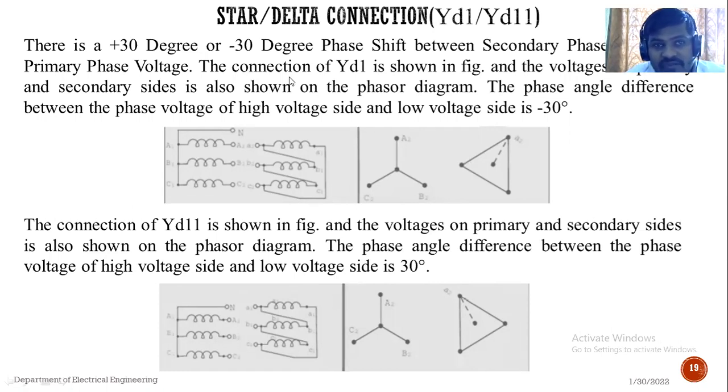The phase angle is leading. Okay, suppose the primary is connected in star. If I am taking one phasor, VR as the reference phasor, and I draw the phasors, then this one is the VB phasor, and this one is the VY phasor. Similarly, the secondary R phase voltage leads the primary R phase voltage by 30 degrees, so this voltage comes here.